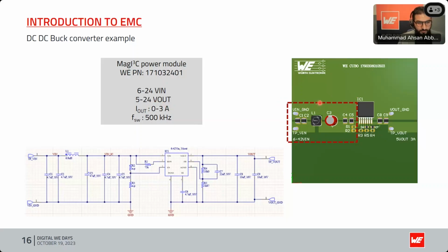You will see some very interesting results, because the use of integrated ICs or solutions is becoming more and more common in the market. They normally need an input filter, so that in the final application or system, you don't get interference from your converters. But the placement of the input filter components with respect to the input capacitors is interesting, especially in the conducted emission setup.